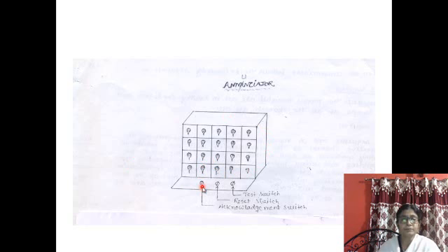Next is the back to normal sequence. That is a completely different process for the process control loop rather than the annunciator unit. The necessary corrective actions should be taken for that particular control loop, and after the correction is over, that particular loop will be back to normal. Then the reset switch will be pressed to turn off the lamp of that channel.